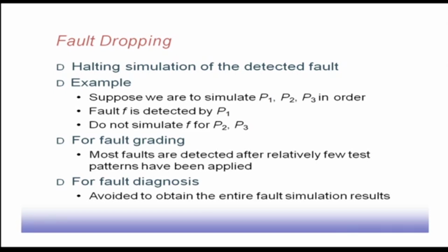Now when we have a large number of patterns, the remaining patterns may not be very effective in detecting many of the faults. So fault dropping helps us, because those faults are already detected, so we do not simulate them further. However, there is another application of fault simulation which is known as diagnosis.